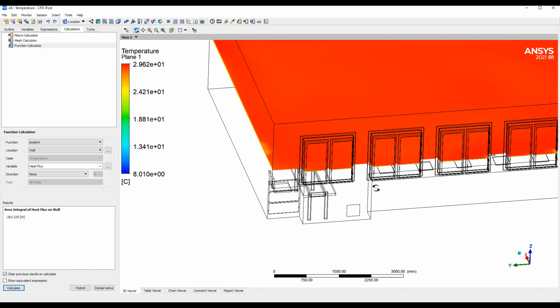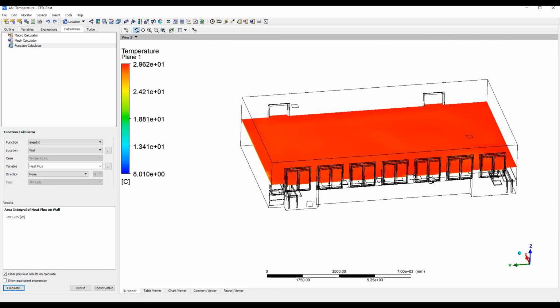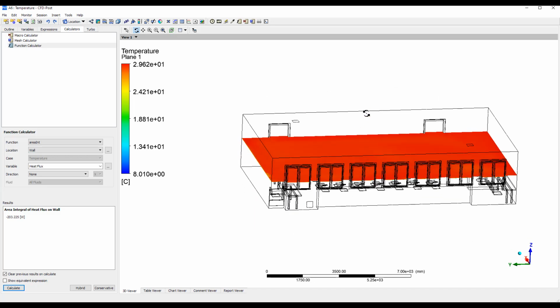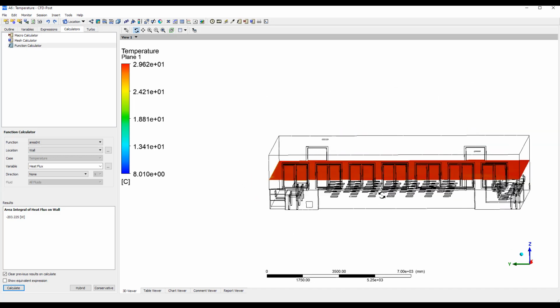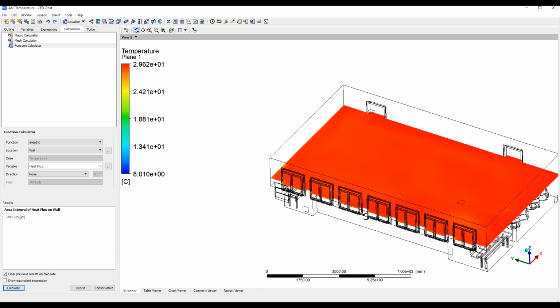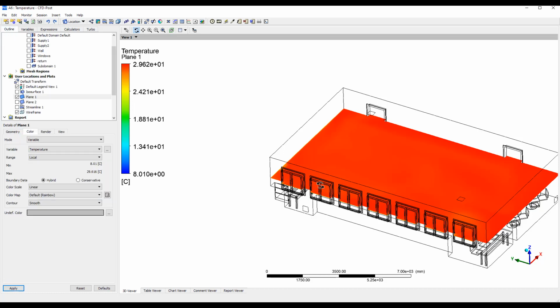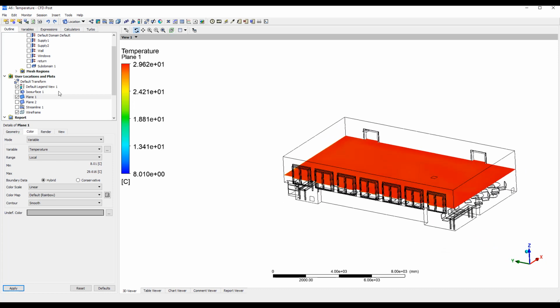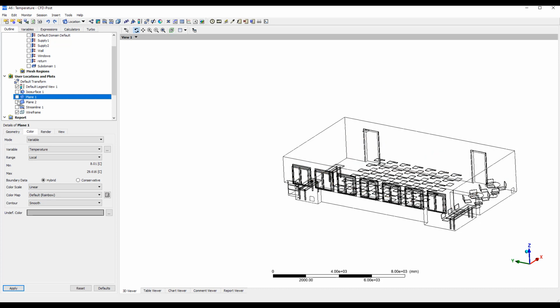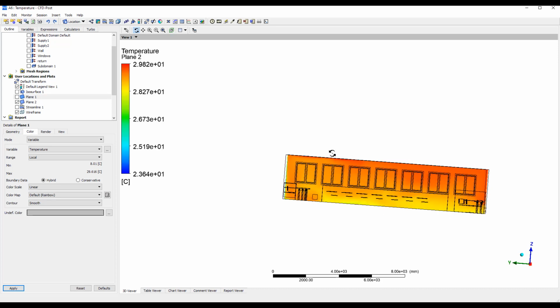In real models, you may want to specify the top and the bottom too, if there's heat loss through the roof or the floor, depending on which floor this is on, and also some of the other walls. But as long as you have good R values, all of this information should be fine. Yeah, so you can see that in this one simulation now, I should also plot a temperature plot like this.